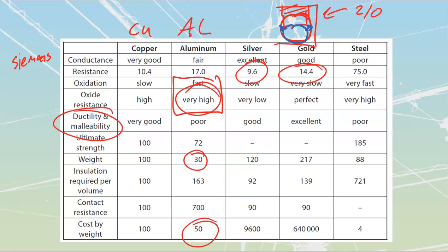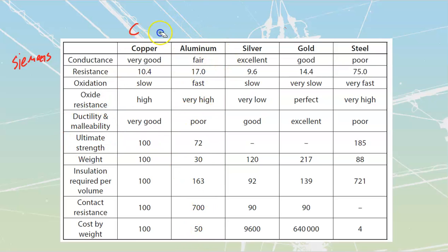There are problems with aluminum. It's not a perfect type of conductor, but overall, it is worth it because it is cheap, it's light, and we can manage it. We can bend it, we can drag it around sites and things like that. Just because something is made with aluminum doesn't mean it's an inherent fire risk. I know some people don't want to buy houses that have got aluminum wiring in there. I want you to just think for a second, if that house has been wired in aluminum since the 70s, and if it hasn't burnt down yet, what makes you think that it's going to burn down the instant that you buy it because it's got aluminum wiring? It's as soon as you start disturbing that aluminum wire that you start to have problems with it. But overall, aluminum wire in and of itself is not dangerous if it is treated correctly.